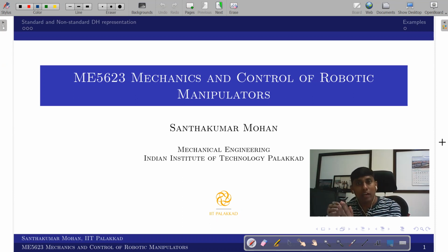Then you travel to the ith axis. The ith frame would be associated with xi, and your xi minus one would have some angle difference. That is what you represent as theta i. Then you see there is a distance between these two, which is what you call di. So if you write the DH or arm matrix, it would have a mix of i minus one and i. This is the basic difference.